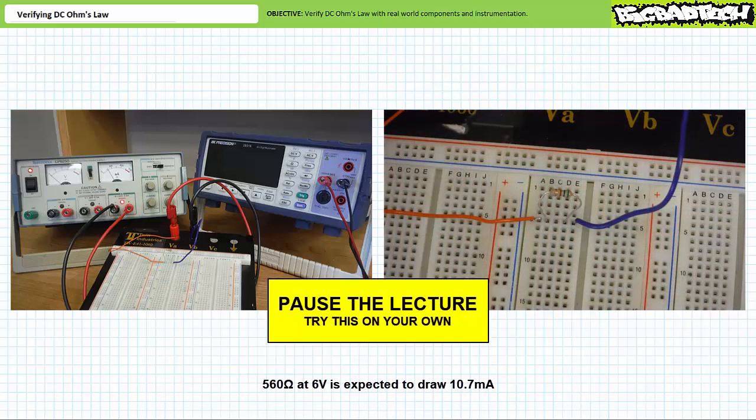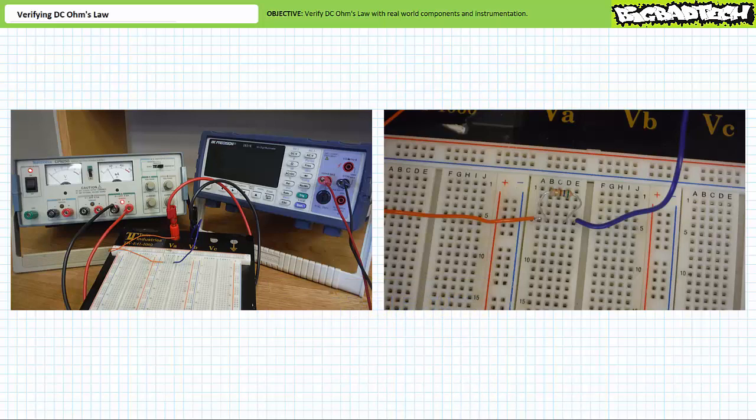By all means, pause the lecture and troubleshoot this circuit. What's wrong? If you're tracking, you should have come to the following conclusion. This is indeed a 6-volt source, and this is in fact a 560 ohm resistor. However, they've built the circuit on the protoboard incorrectly. Note, both terminals of the resistor are landed at the same node, 5A through E. Additionally, both the positive and negative terminals of the source are also landed at the same node, 5A through E.